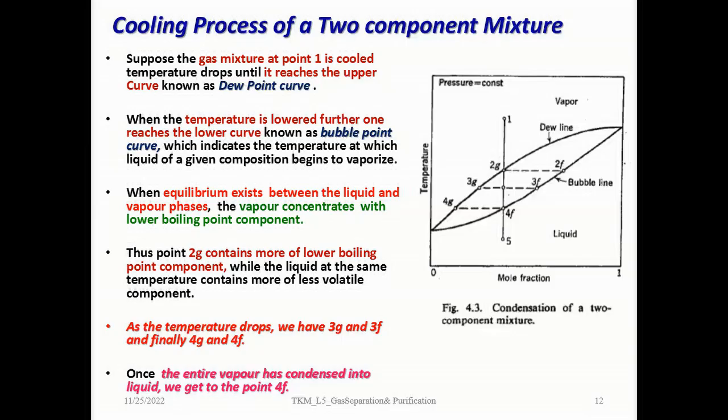Okay, you start gradually cooling this gas mixture. When you do this, first it touches the dew point line where the gas condenses into a liquid. The gas phase will have exactly the same composition. At the same time, the liquid phase will have more of the oxygen component.